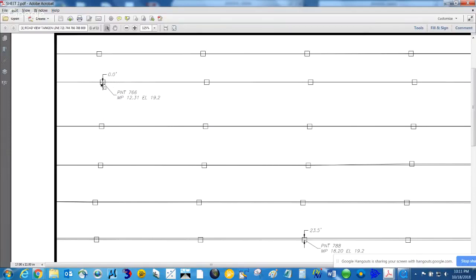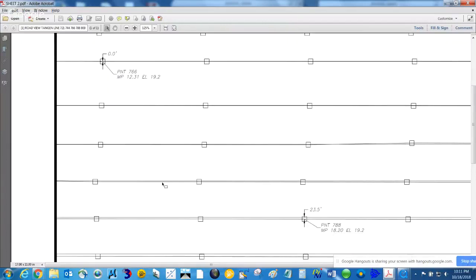And here what we're doing is saying at that GPS shot, we're going to create a tangent line, just like we would do with a theodolite or an auto level, and construct a model where we strike out that tangent in either direction. And you'll start to see it deviate or separate.